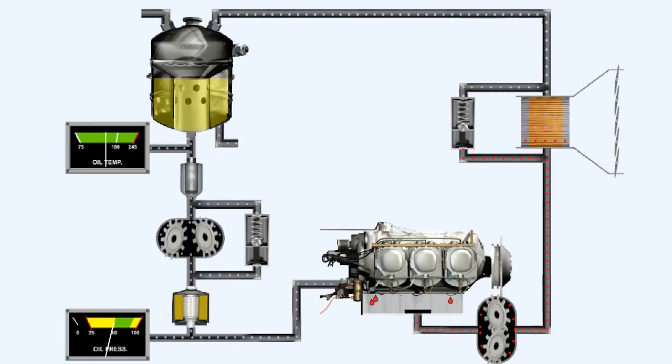Fluctuations in pressure could be the result of either low oil levels or system faults. Small fluctuations of the oil pressure gauge needle, either side of the desired pressure, may be indicative of a sticking pressure relief valve. This would cause the pressure to first build up beyond the optimum level, then subsequently, when the pressure reached a point high enough to overcome the stiction of the valve, it would open, dropping the pressure momentarily below the correct level. Then the cycle would start again.